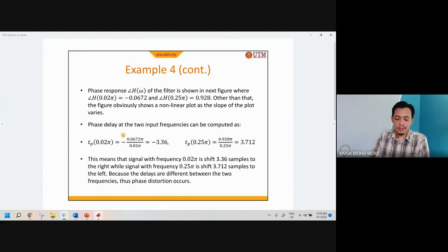But what is the basic point now is phase. We will see the effect in the time domain, some delay. We have seen a zero phase system, which doesn't give you any delay, and a linear phase system. A linear phase means that you're going to have a delay, but the delay is consistent on every frequency, on all frequencies, which is fine.